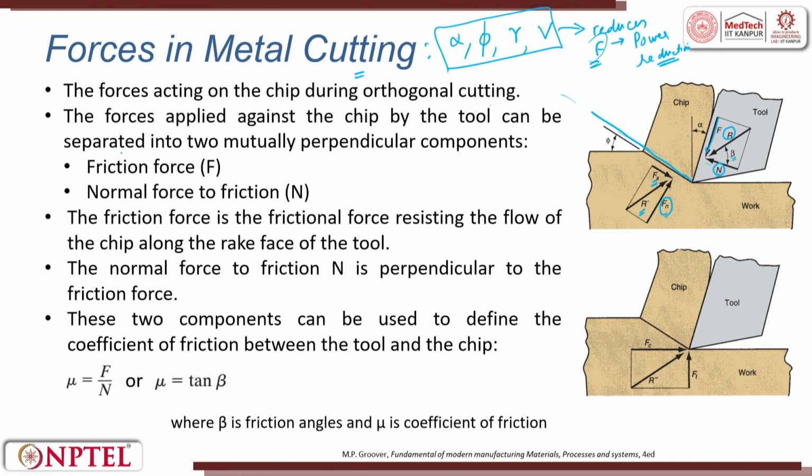So, let us go by reading through the slides. The force applied against the chip by the tool can be separated into two mutually perpendicular components: friction force F and normal force N. The force applied against the chip by the tool can be resolved into F and N. The friction force is the frictional force resisting the flow of the chip along the tool face.